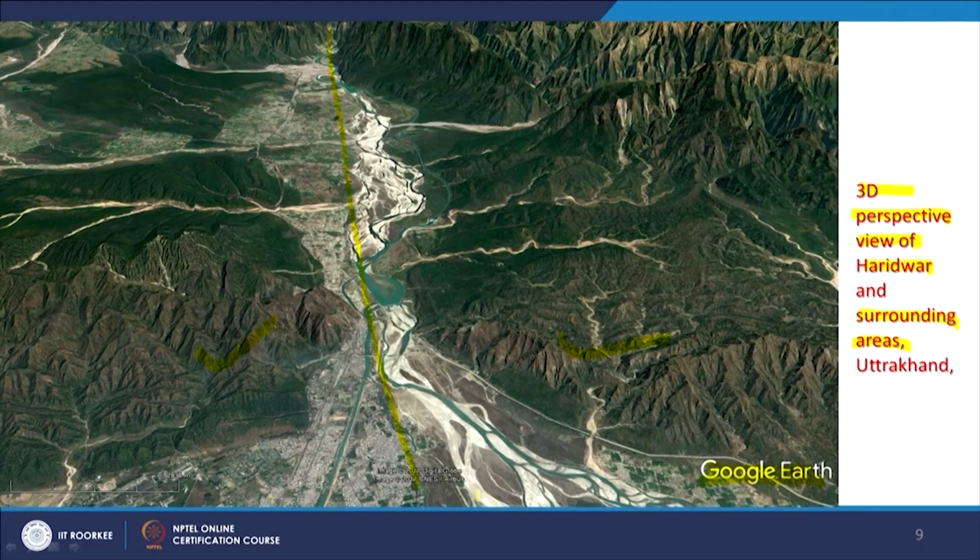So depending on what somebody is looking for, if a civil engineer has to find a place where a new bridge can be constructed, then before going on the ground, a study can be done initially for feasibility purposes using whatever is available, like Google Earth. And once you have broadly identified a location, then a detailed view can be generated with high spatial resolution and high digital elevation models for that particular area where further study can be done.